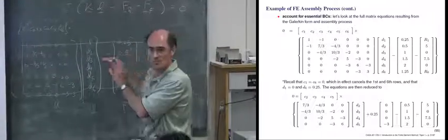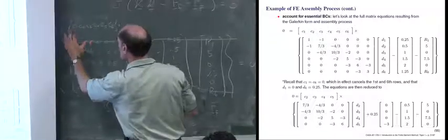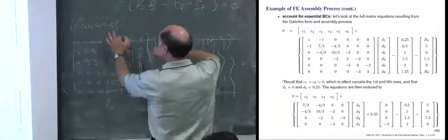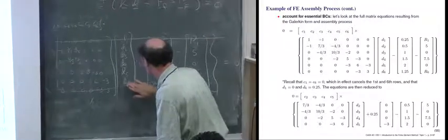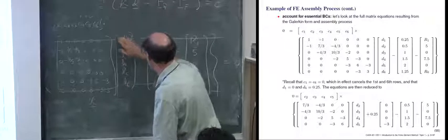You're doing a matrix multiplication. C1 is 0, cancels the first row. C6 is 0, cancels the last one. I should be careful here. Let me not do it on the D, only on the K, the little f, and the big F. So you'll see here, R1 and R6 are unknown, but right now it doesn't matter. They get canceled out.